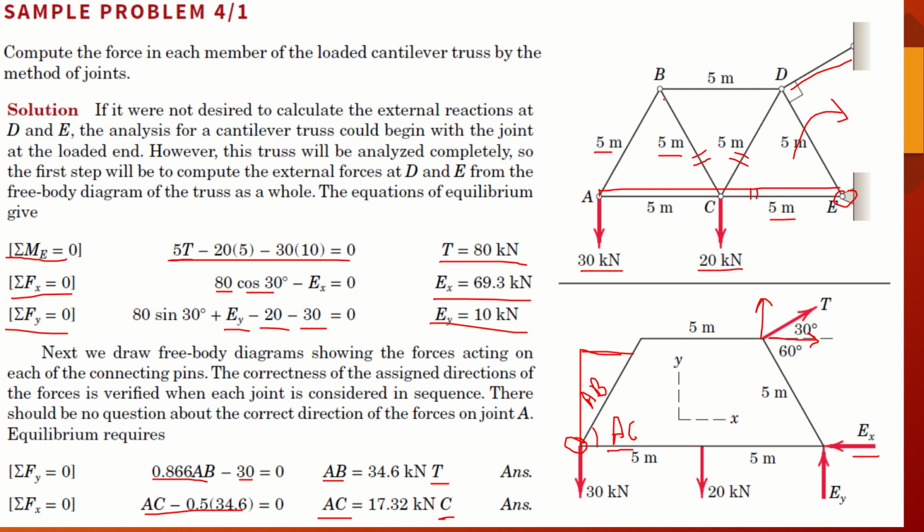If you look at joint B, we have two unknowns again, that is BC and BD. So two unknowns are safe. Since, as we know, this component AB is known, as we have calculated by solving joint A, we are going to move to joint B now.